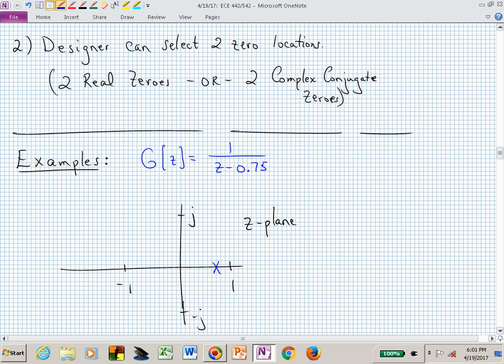If you had a proportional controller, though, you're going to have an offset between your reference input and the output. And maybe you don't want that. Maybe you want to have 0 error to a constant input. I put in 4, I want my output to go to 4. I put in 3, I want it to go to 3. I put in 12, it'll go to 12. How's that going to happen? How do I guarantee that I have 0 error due to a constant input?